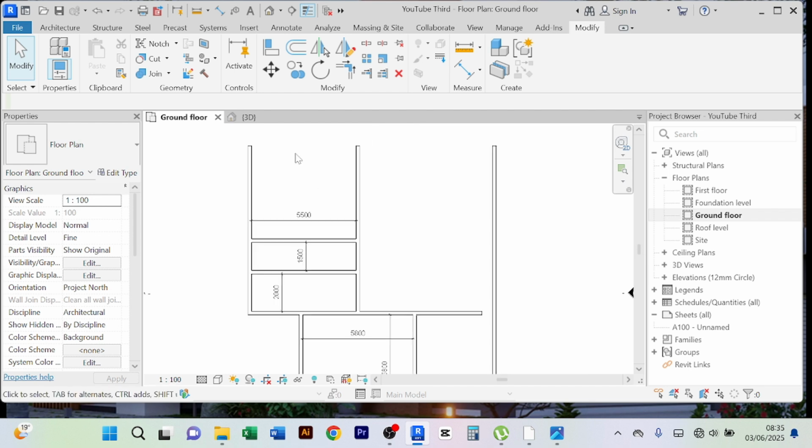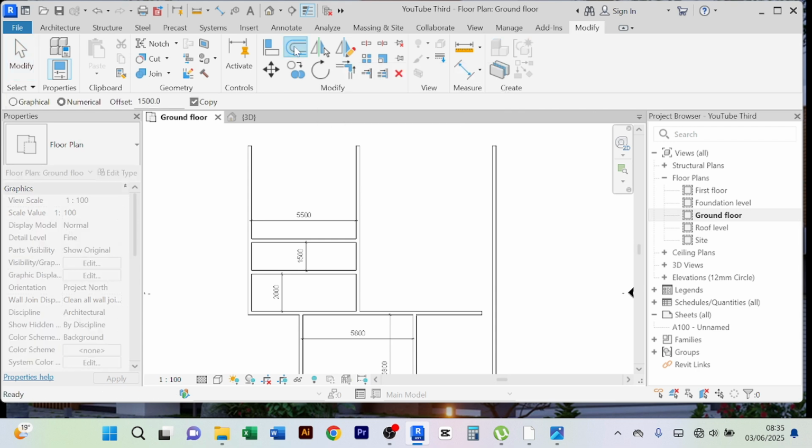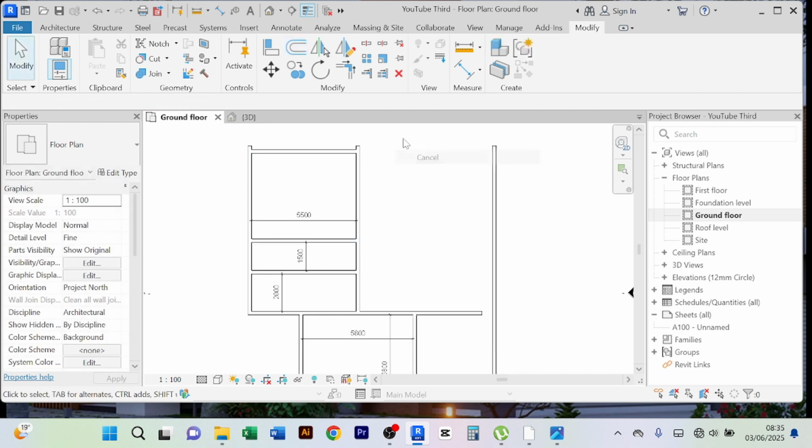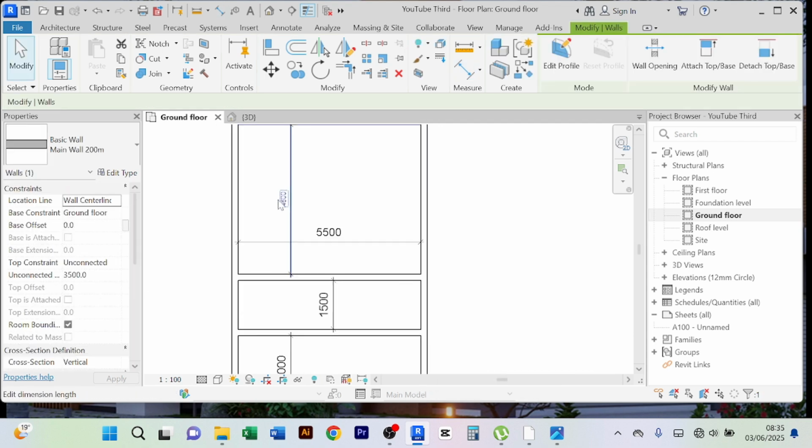So we're going to offset 4.8. Come to the offset. By now you should know the offset tool or the OF tool. So we're giving it 4.8 here. I'll go with that. I'll offset this side. But of course, you know this is not 4.8. You come to your aligned dimension. For measuring, you measure the two parallel lines, and then you click on that, you give it 4.8.